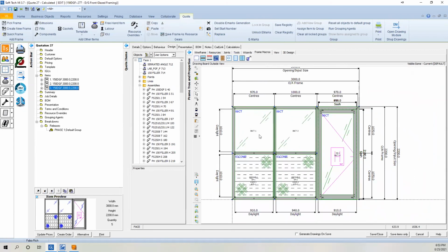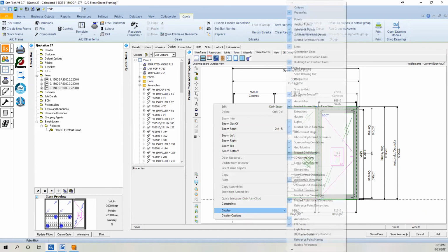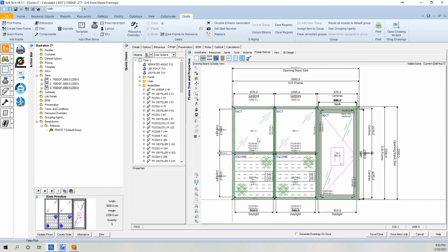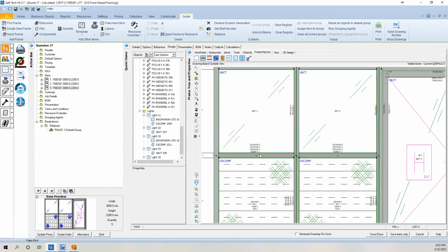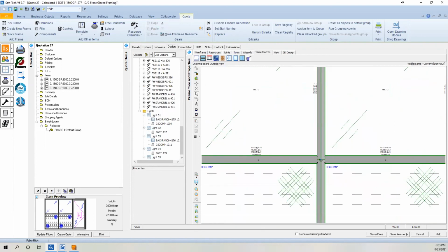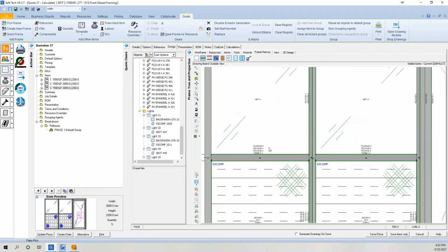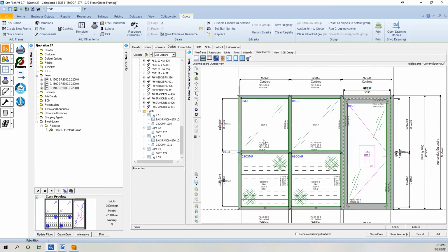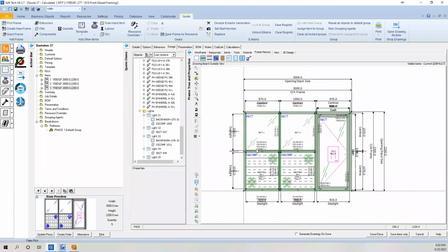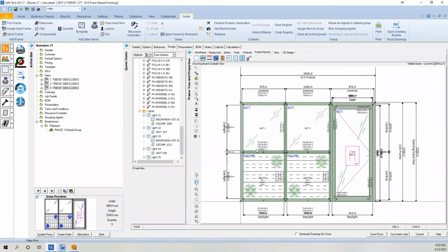So every piece which is unique, whether it's a glass or an extrusion, will get an E-mark in the software. If I show you the extrusion E-marks, you can see we have FS1105-BD2, there will be BD1, BD5, BD7, all these with different size and machining operations, they will get different E-marks so that we can know which piece goes to which elevation and accordingly fabricate.